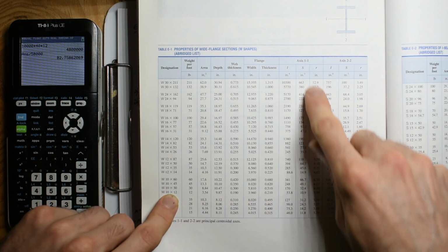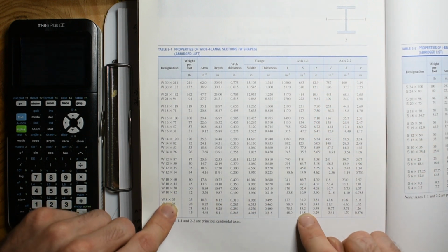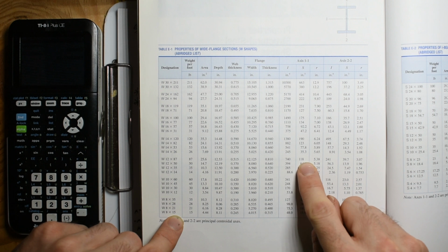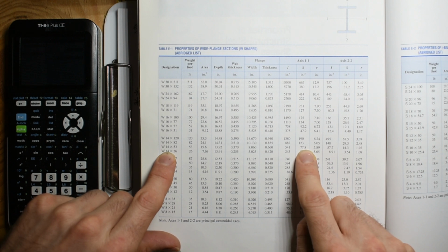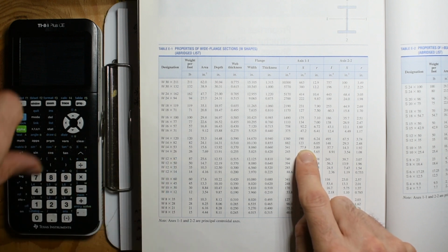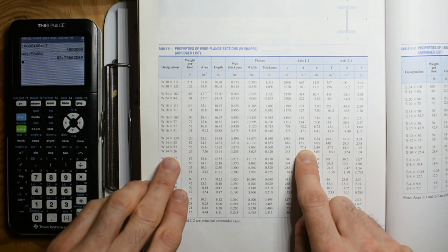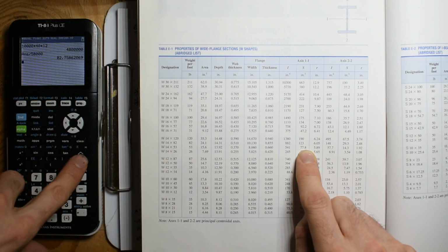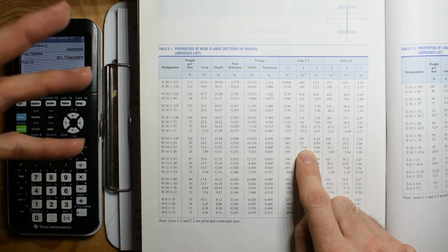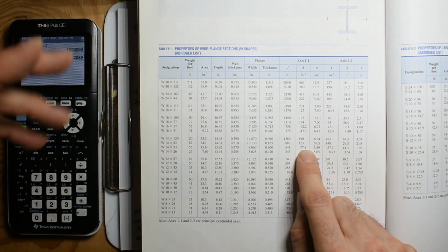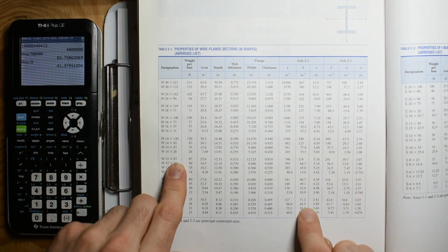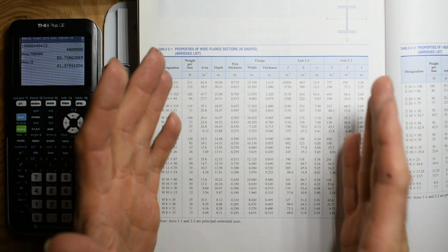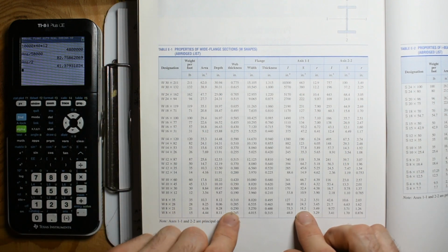Anyway, so S of 82. So I'm just going to go down here, and let's see where we get the first one to say 82. This is 100. So maybe like right there. Oh, but check this out. Do you think I'm just going to drive across one of them? No, I'm going to have 2. And we already said 10,000, which is plenty for a 5,000 pound car, whatever. And then so my S value only has to be 41. Never thought about that. If I put 4, 2 under each wheel, I could get down to 20.